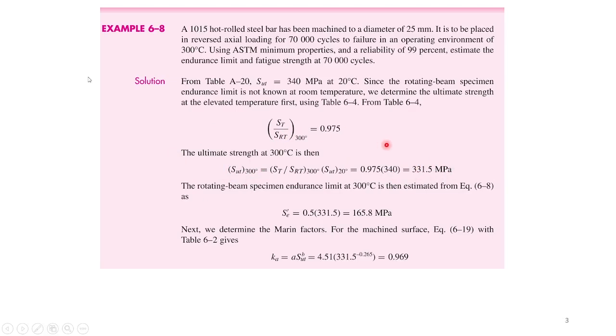Okay. Now you can calculate the endurance limit. This is the corrected ultimate tensile strength. So you can calculate the endurance strength or endurance limit. I know that for steels there is a relationship between the endurance limit and the ultimate tensile strength. SE is equal to 0.5 S ultimate, provided that this S ultimate is less than 1400 megapascal, as we took in the first lecture.